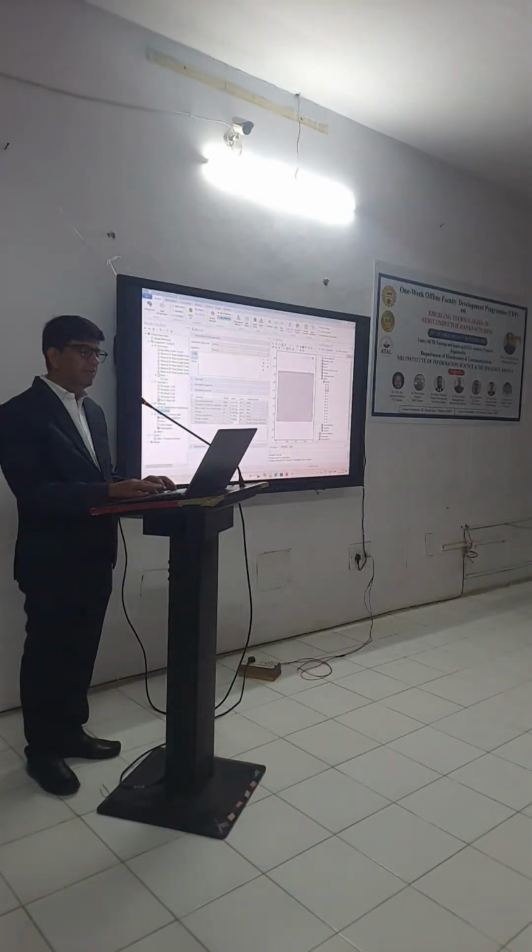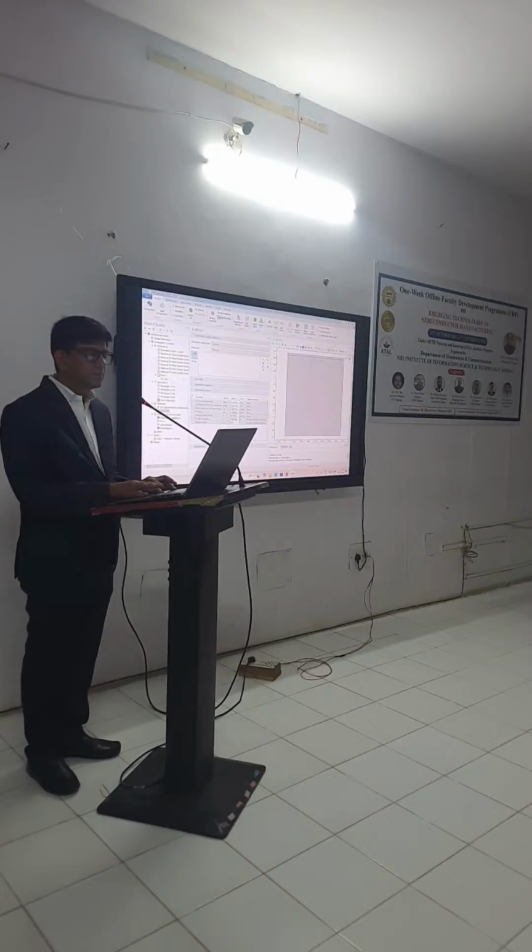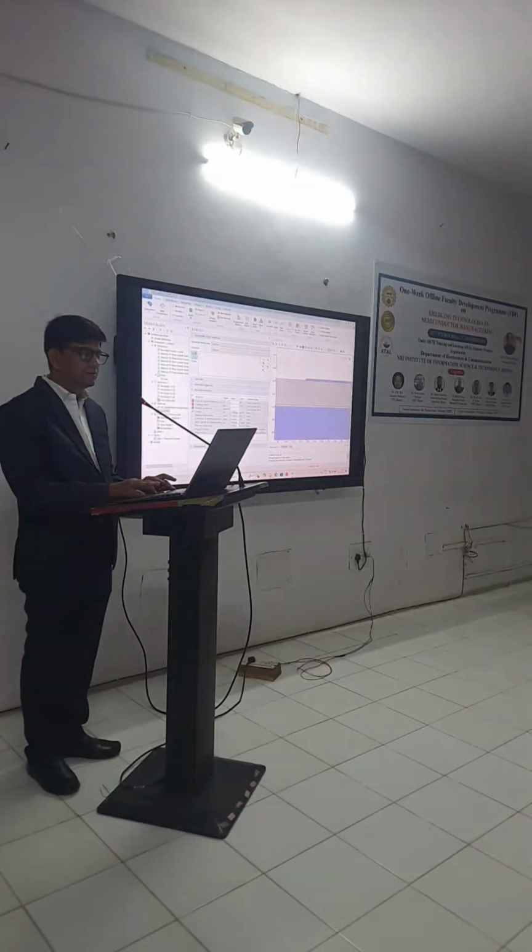define a layer. Which layer is my gold layer? I have this as a gold layer, and this one is the PET, so I define these two materials as my electrode, and then what is left? The piezoelectric layer. So I have to define the piezoelectric layer as ZnO.